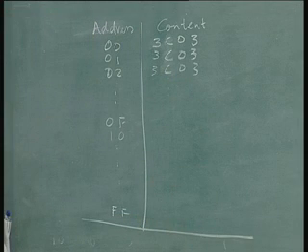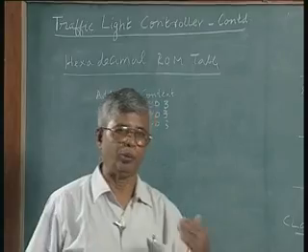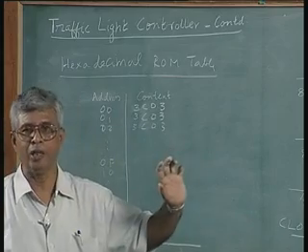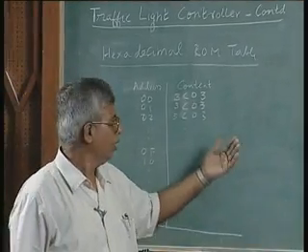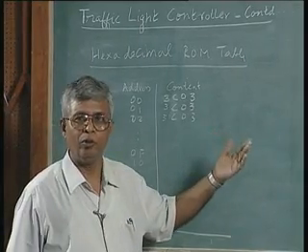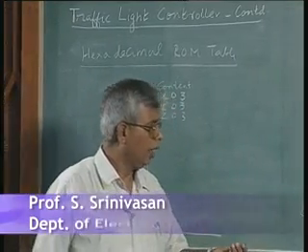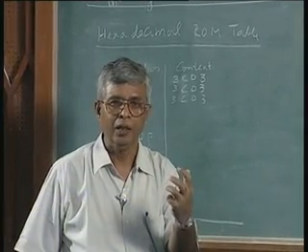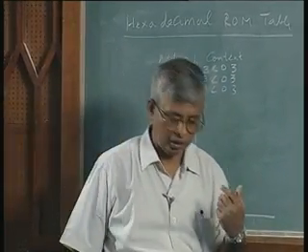And then you can go to the next step and have a programmable array logic. We will not go over all of those again, because we have already discussed the difference between the PAL approach and the ROM approach. The PAL will have a PAL table, which is a simplified form of a ROM table, because redundant entries where there is no activity will be removed. PAL will have fewer rows or fewer product terms. Another advantage is that the registers are included in the PAL. I can have a PAL or a PLA, usually a PAL, in which the register is part of the device.